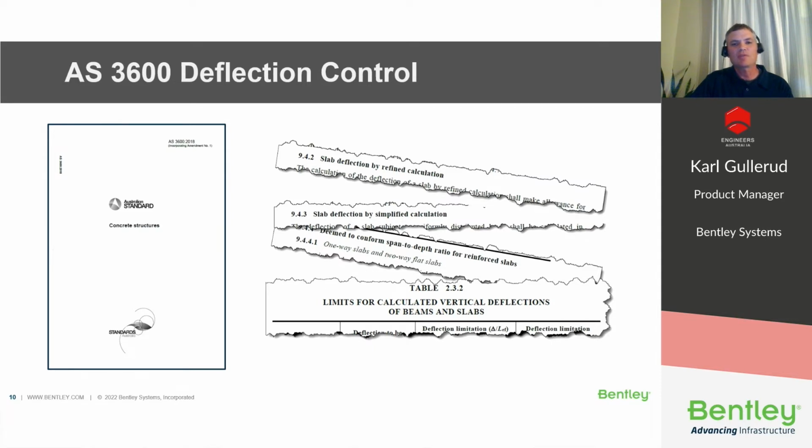A simplified method, which is based on an effective span to depth ratio. That method also accounts for time-dependent creep and shrinkage effects. And then finally, a refined calculation method, which is an advanced deflection calculation method like the one referred to in the introduction.